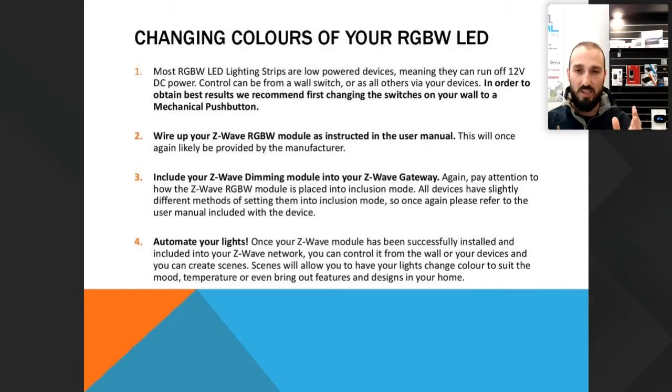They do tend to start to play around and mess around with the device. If they want to swap over to a push button, which is what we recommend, you can change the settings inside your device settings using your gateway. So rest assured, you've got both aspects covered in that one. For dimming and RGBW, however, we do recommend that you use the push button.